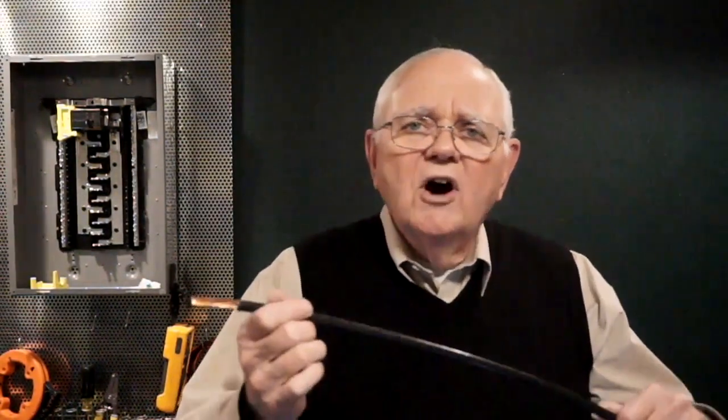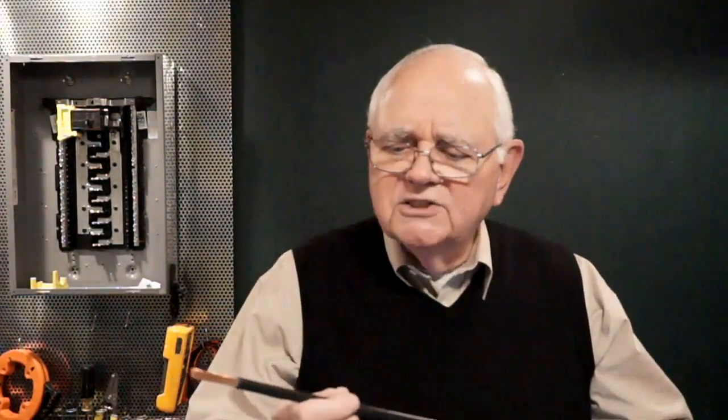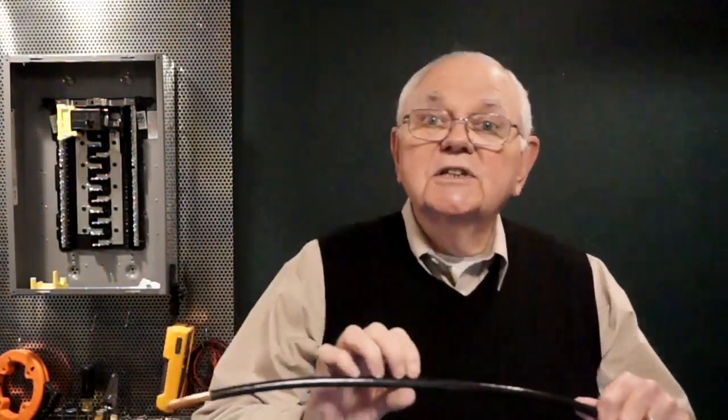on this THHN. Now, the THHN manufactured from PVC then, it quite often has a nylon jacket on the outside of it. The nylon jacket does a couple of things for us. One, it gives some physical protection to the conductor material, which is very important because as we pull this conductor through our conduits and so forth, I don't want to nick the insulation certainly and thin it out or even expose any of the conductor material. So the nylon jacket gives me that physical protection.